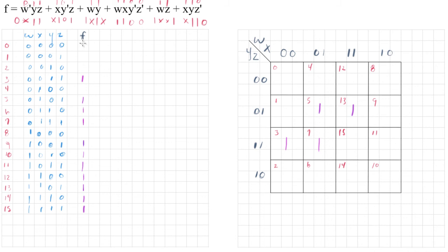expression. So that means that anything that wasn't marked is going to be a 0. It's off. And in the same way that we're marking those with zeros, they're going to be marked 0 on the K-map. So we have 0, 1, and 2 are zeros. 4 is 0. 5 is on. 6 is on. Then we've got 7. Oh, we already marked that. Then to 8. Off. And the rest are 1s. Okay.